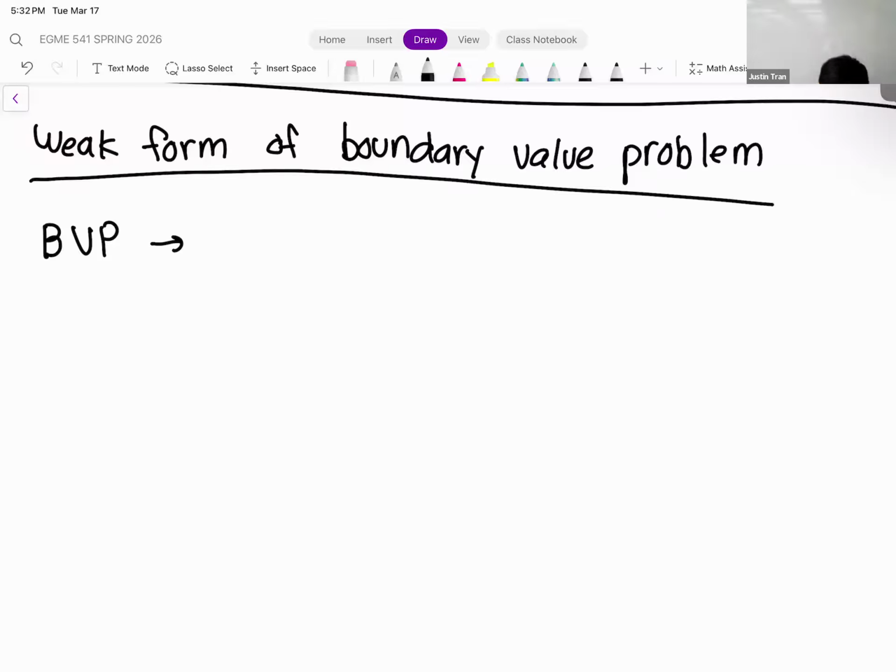there's essentially three components. On the one hand, we have our geometry, or another way you can say it is that we have our domain. That's going to be the region on which we want to solve our problem. In general in finite elements, your domain is usually going to be a three-dimensional domain, sometimes a two-dimensional domain. That's obviously going to be defined by your CAD geometry if you're talking about using ANSYS. But in 1D, usually your domain is going to be a lower bound for x and an upper bound for x.